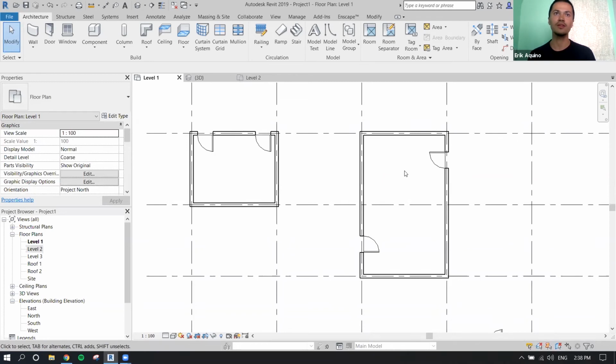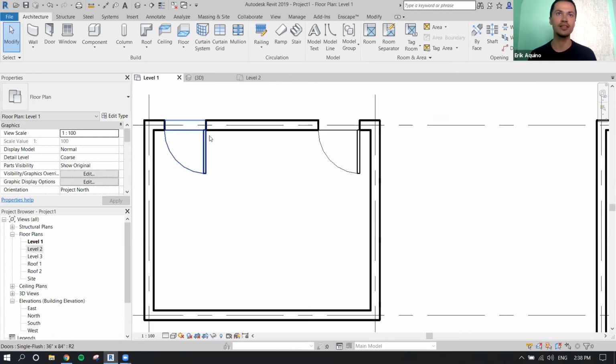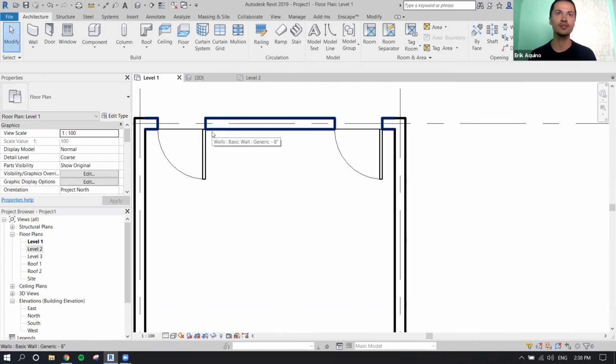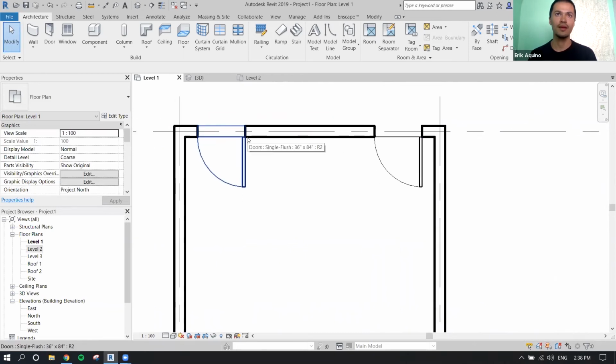Another way we could add it to our selection is hover over the edge. And the problem is we have a lot of elements on top of each other at this point. So what we could do is press tab to cycle through different elements which you could select. And you'll know what you're selecting based off this bottom corner.